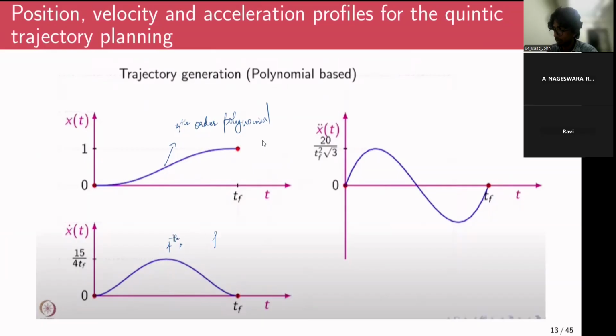So here, this will also be a very smooth curve. And the maximum velocity, the peak velocity that you can have is given by this expression 15 by 8 TF square, and the time that this maximum velocity would occur would be this TF by 2. It's easy to verify that on our own.